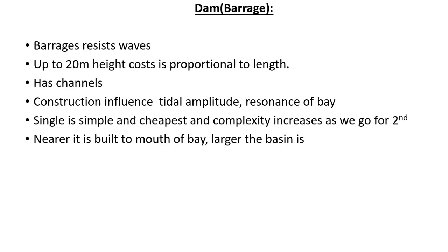Okay, so this barrage has to provide channels for the turbines in reinforced concrete. To build these channels, a temporary cofferdam is necessary, but it is now possible to build them on land, then float them to the site and sink them into place.